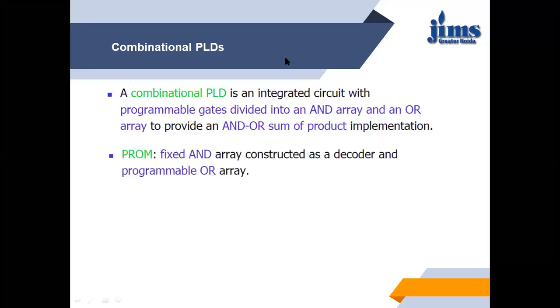Now first is the PROM, what we have studied. Fixed AND array constructed as a decoder and programmable OR gates. So the work of the decoder is to provide 2 raised to the power n AND terms, that is the product terms, and OR gates are used to sum the product terms. That is the PROM. We have PAL, programmable array logic, which has programmable AND array and fixed OR array. In case of PROM, AND array is fixed. In case of PAL, OR array is fixed.